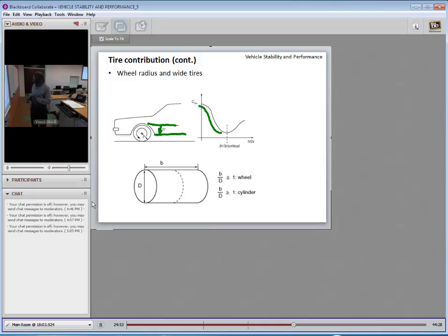So what we have then is the larger the radius of the tire, and the smaller the housing, that we will have various effects. The combination is such that the drag coefficient depends on the ratio of this H to the radius of the tire. H over 2R, the larger H over 2R is to a critical value.